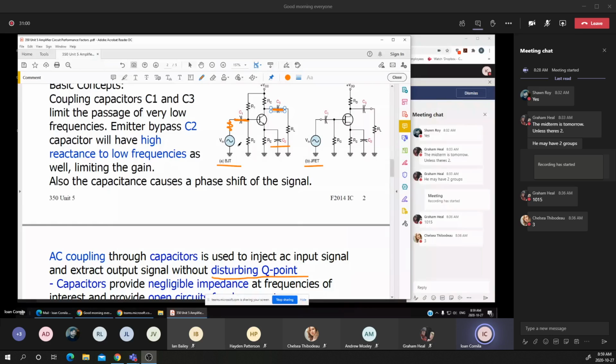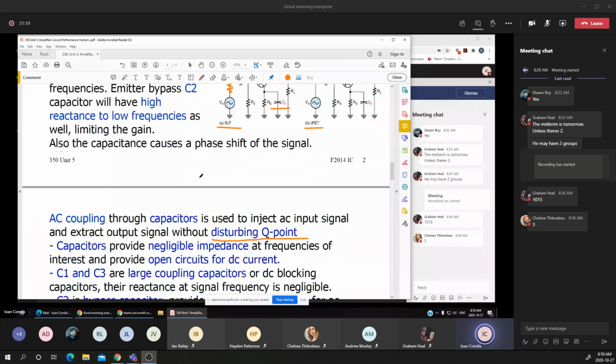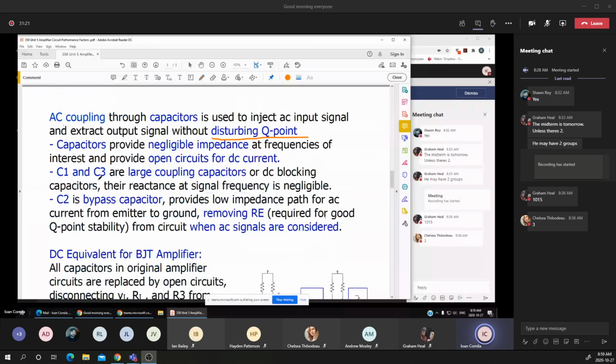And in AC analysis, I will give just an idea about the AC analysis. The capacitors are short-circuited and the voltage sources are replaced with a short circuit. Now, I mentioned that the first two are pretty large value capacitors, and those are coupling capacitors.